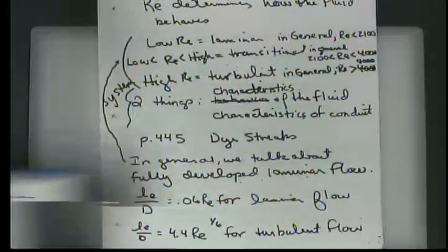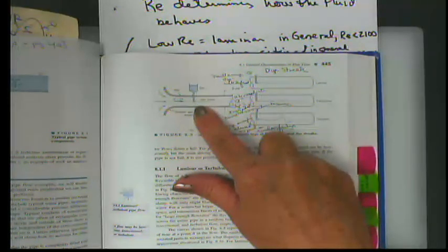What happens in this experiment is we have flow entering a smooth, well-rounded entrance. The well-rounded entrance just prevents any entrance effects or minimizes entrance effects. And somewhere where we're in completely developed flow, away from any of the entrance effects, we have a small pitot tube in which a dye streak is emitted.